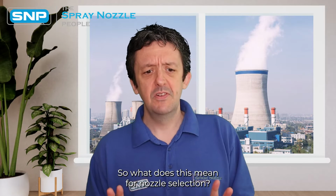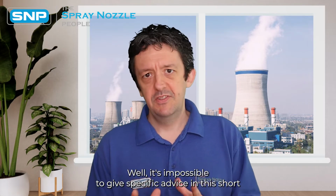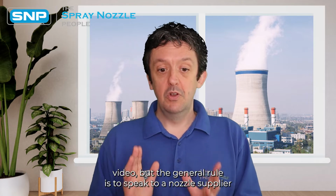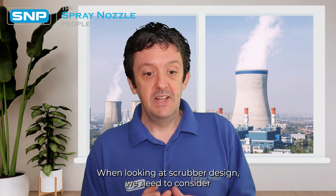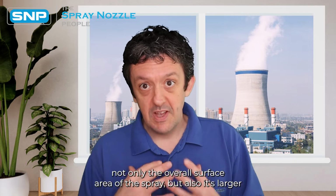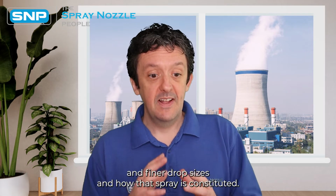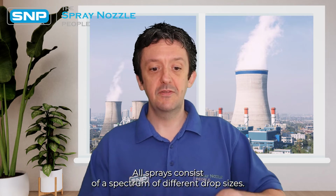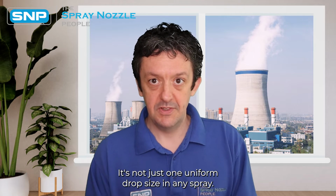So what does this mean for nozzle selection? Well, it's impossible to give specific advice in this short video, but as a general rule is to speak to a nozzle supplier that understands all of this. When looking at scrubber design, we need to consider not only the overall surface area of the spray, but also its larger and finer drop sizes and how that spray is constituted. All sprays consist of a spectrum of different drop sizes. There's not just one uniform drop size in any spray.